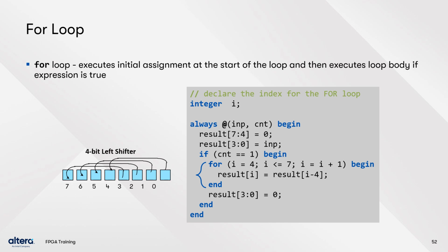In C, you can alter the count variable within the loop, but in synthesizable Verilog, you cannot alter the count variable within the for loop. In hardware, loops are unrolled. It is important to consider which function resides in the for loops. If the above example included a multiplier inside the for loop, 4 multipliers would be implemented in hardware.